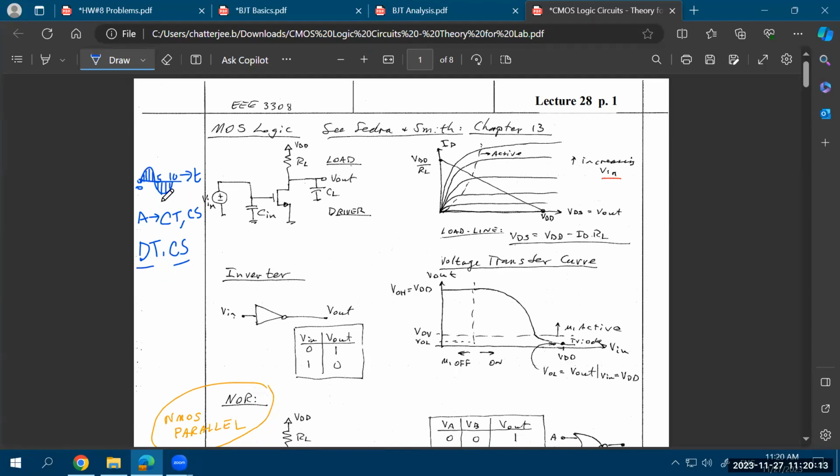But now let's say you have also sampled and quantized the value of the signal as well. In that case, it's called quantization. The way a quantized sine wave looks is that if this was your original sine wave, and let's say at certain points you're quantizing. At 0, your value is this much. At 1, let's say your value is this much.